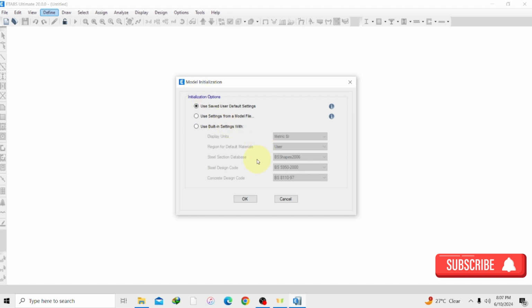There are various options here. This dialog box is where you set your units of measurement, the code you're using for the design, and other things. This right here is the user default settings. This one is just the default settings in ETABS. In case the selected codes or units of measurement are the same as what you use in your design, you just stick with it and continue. But if it's not the same and you want to change it to your preferred codes or units of measurement, we have another option here, that's the use built-in settings with. So you just have to click on this option.